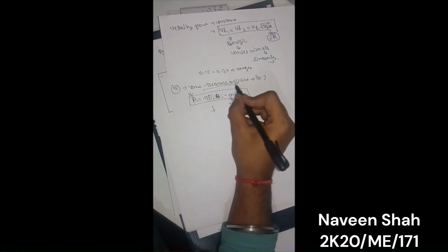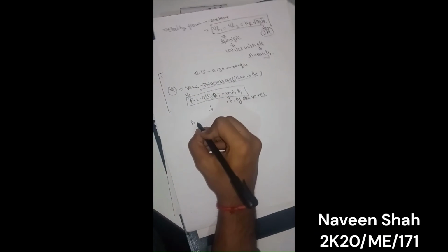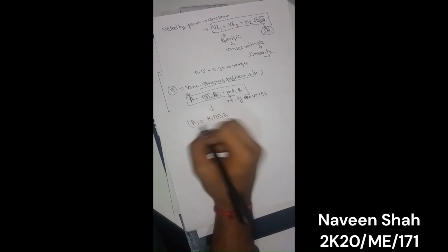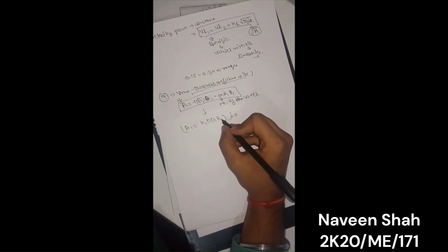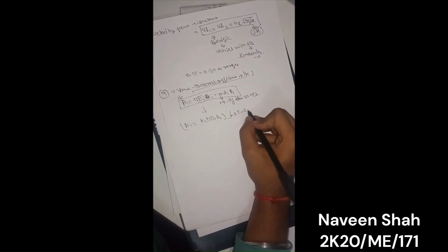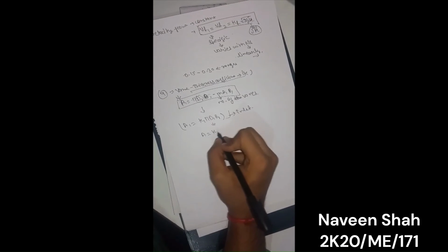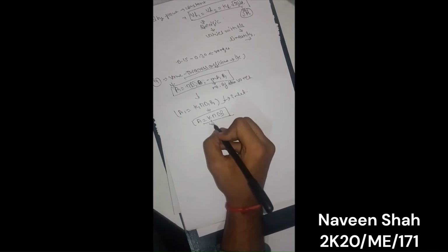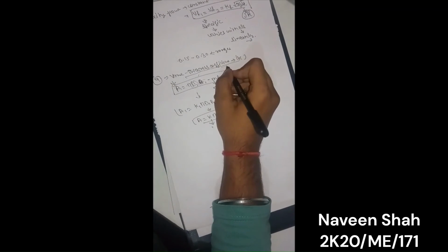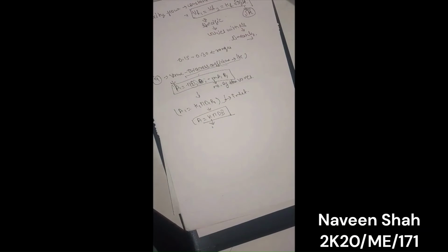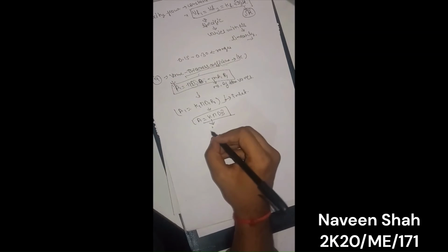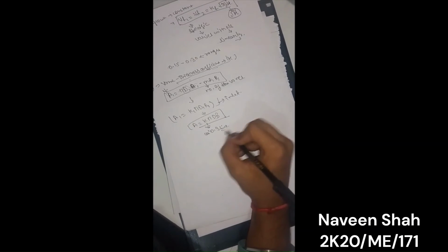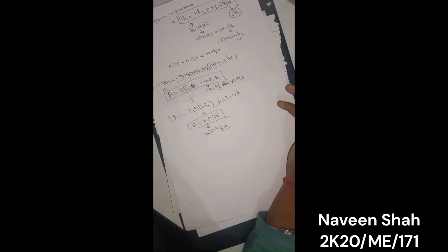But when we consider the vane thickness coefficient, this formula reduces to A1 equals K1 pi D1 B1. The suffix 1 is for inlet. So the general formula is A equals K pi D B, where K is the vane thickness coefficient. Its value is generally taken as 0.95, because at this value it gives the appropriate geometry for the runner.